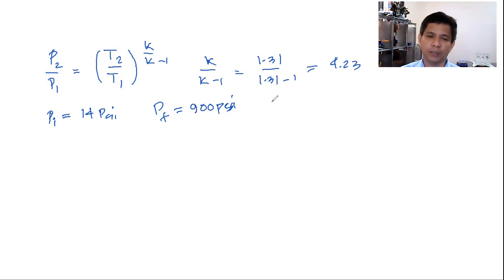You have three compressors in series. So what happens if you have three compressors in series is, if this is your final and initial pressure, you're going to take the cube root to get the actual pressure ratio. That's it, just take the cube root.